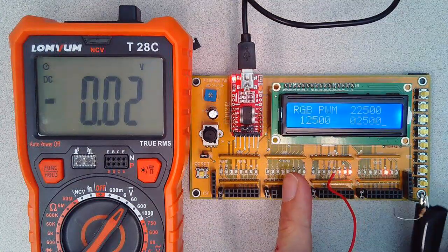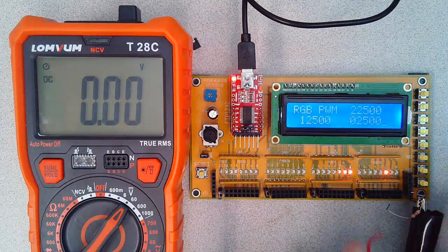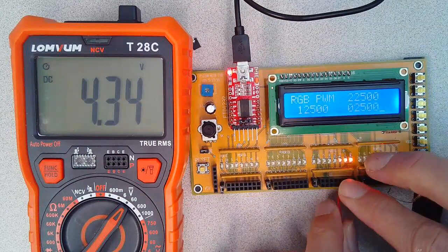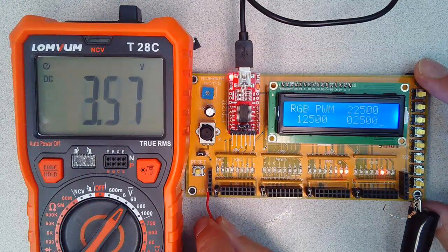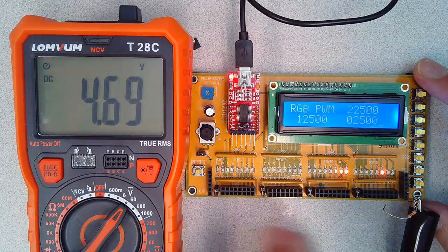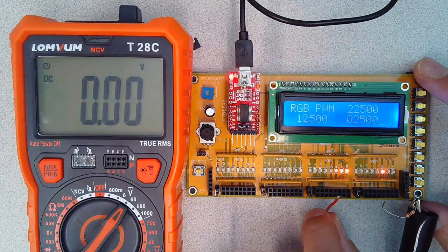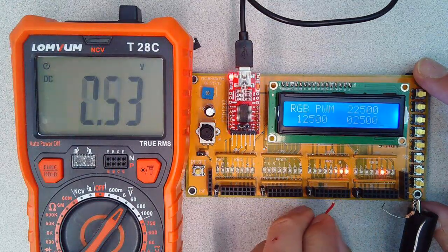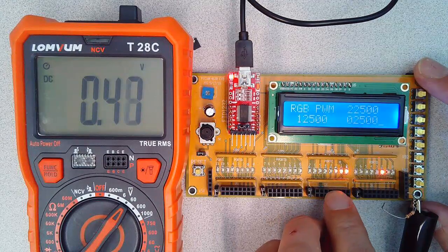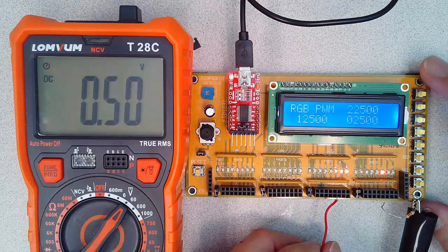Okay, to illustrate the PWM, you can use a voltmeter. So this displays the average voltage. DC is average. So if I measure it on RC0, this is 4.3 volts. Just back up for a sec. This is 100%. That's my power supply, 4.9. This is 90%. 50%. 10%. So DC measures average.